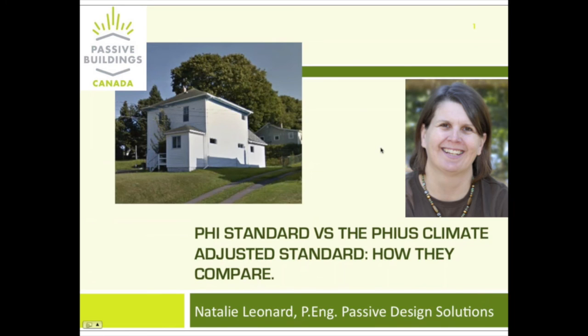Great. And Peter Schroner asks, was the heat pump domestic hot water drawing heat from the indoor air adding to the heat load an issue? Yeah, another good question. There's a mini calculator, and I believe this is in the resources page on PHIUS as well, that basically says that for a certain time of the year, you're definitely drawing heat out of the building and cooling the building that you're having to replace with electric baseboard heat.